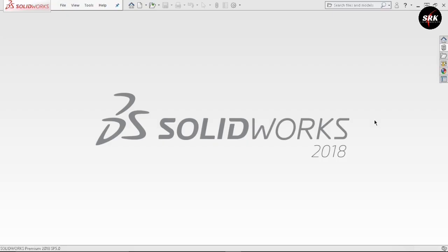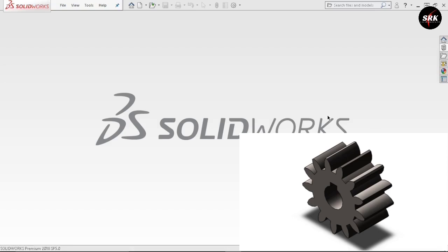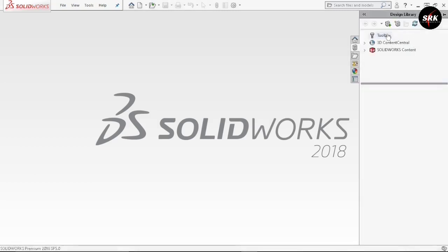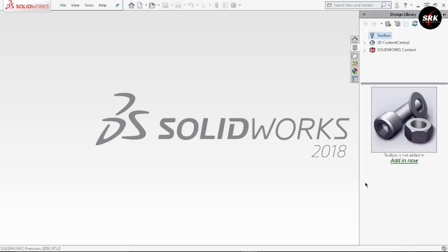So guys, we are going to start with the designing of a component with the first component as a spur gear. So for designing the spur gear, we are going to take the help of the design library. At your right side, you will get this option of design library. In this, select this toolbox. If you have not added your toolbox yet, you will get this kind of option. Just select add in now.